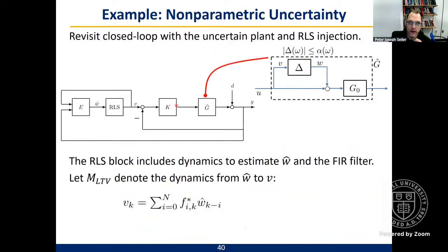So now let's come back to our feedback loop. We've got our classical controller. We now have a model where we've got the design model with a description of how much model error there is. Our recursive least squares, then we've got an estimator. This estimator has built into it what the design model is. That's hidden in here.